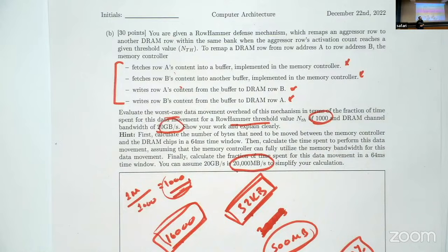I have a question about the fact that you can do the attack on the 16 banks in parallel, because from my understanding, if you can only send the activations every 64 nanoseconds, it's to one specific row, like you can't send to all 16 rows at the same time. Yeah, so the assumption here is that the 64 nanosecond is for targeting the same bank.